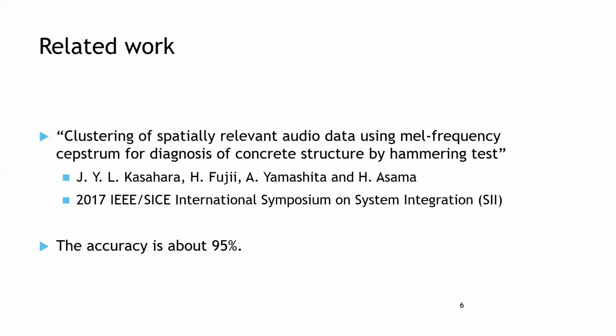I will introduce the related work of the hammering test titled Clustering of Spatial Relevant Audio Data using Frequency Cepstrum for Diagnosis of Concrete Structure by Hammering Test. In this paper, the authors present a supervised learning approach to the automation of the hammering test for the diagnosis of concrete structures, among others. The accuracy is about 95%. But this research is about the hammering test of concrete structures, and we do not use this method because our research is about the hammering of tiles.